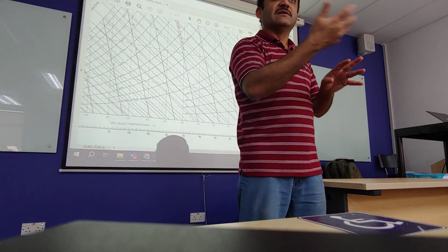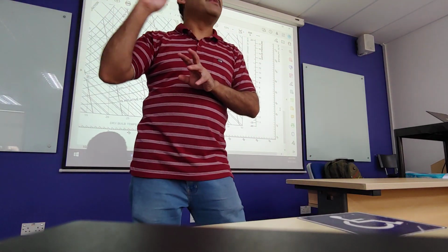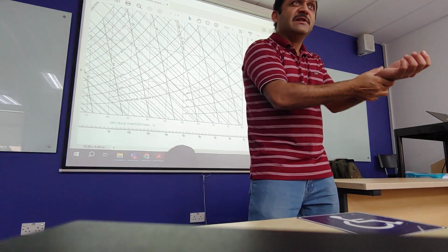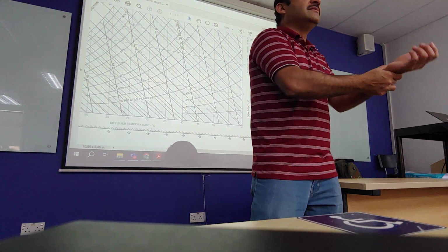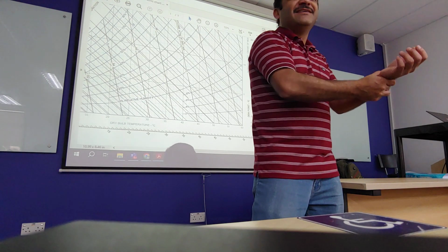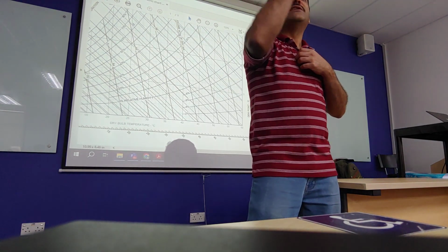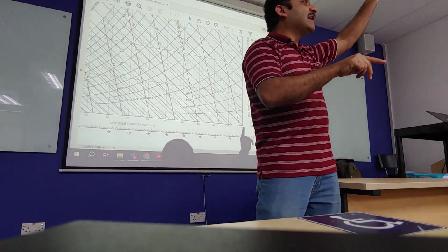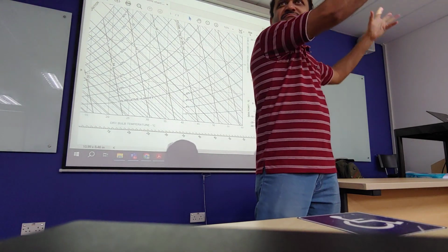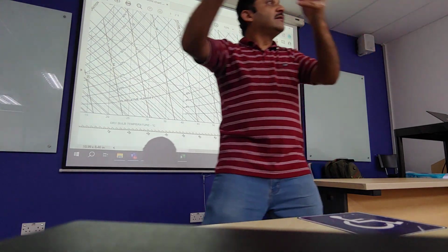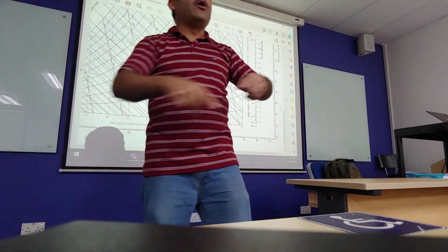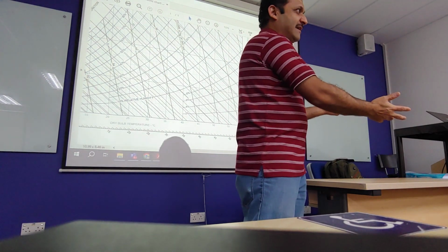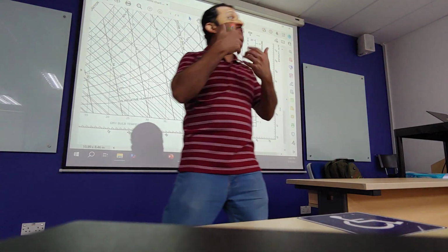They're doctors, like we are doctors. Engineers are doctors of machines. Always remember that. Doctors feel the pulse. You've got a stomach upset, some bug, that's what they say. What do we say? We look at the temperature, pressure, humidity, all of that, and say most likely the filter is clogged with some rubbish, or the blower is not working well, or the refrigeration chiller system is running low on refrigerant. These are the things that we diagnose.